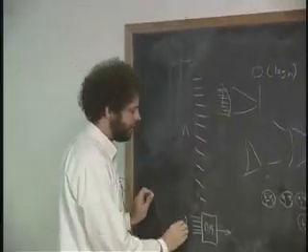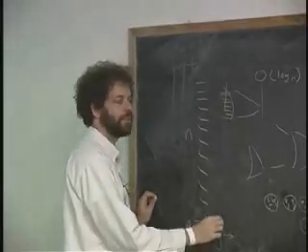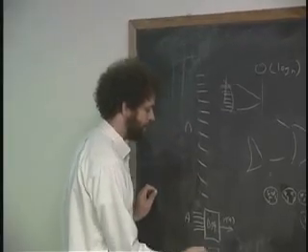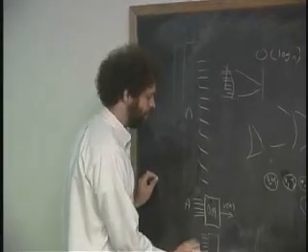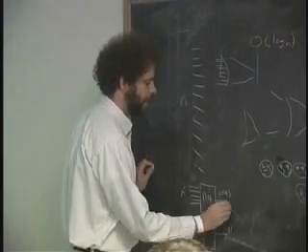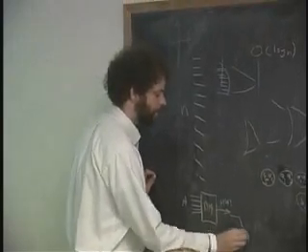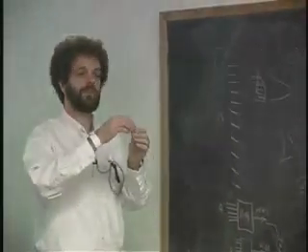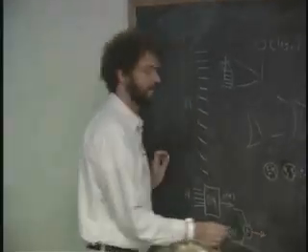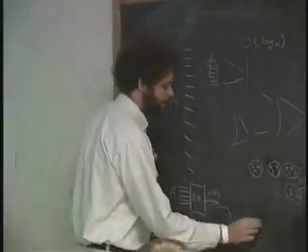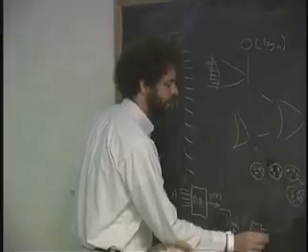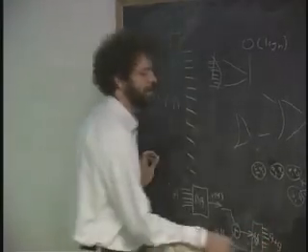So here's A that goes in here, and here's a voltage that corresponds to A. Then I could have another digital to analog converter here that would take B and produce a voltage corresponding to B. Then I could put it into an analog device to sum them, which is similar to putting the 2 pieces of chalk right on top of each other. And then after I got an analog voltage, which was the result, I could put it into an A to D converter, and I could get the sum of A plus B. And don't laugh, because people have actually built this.